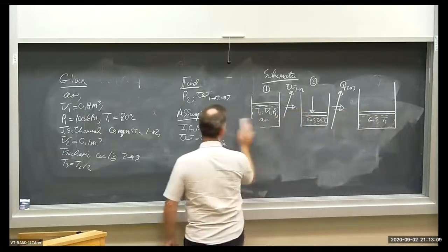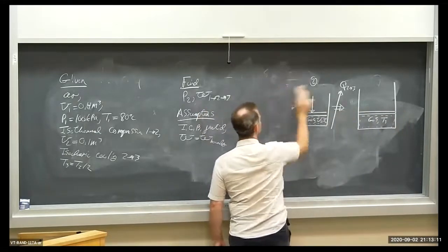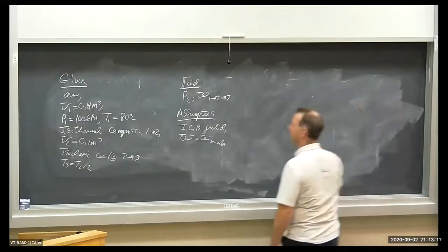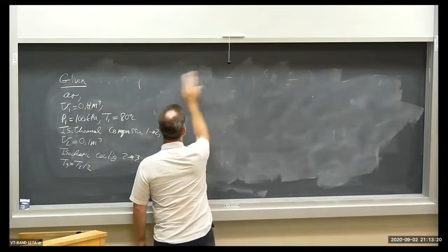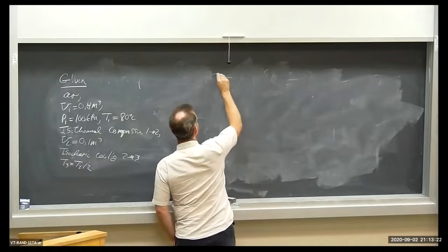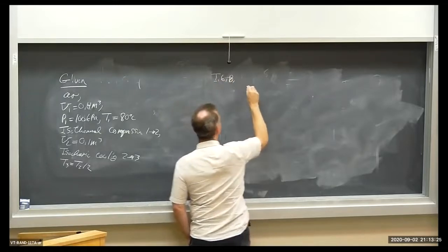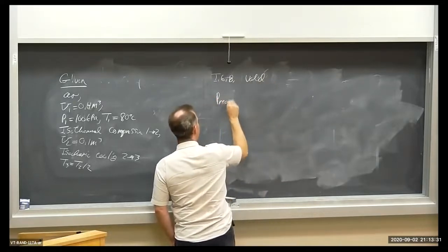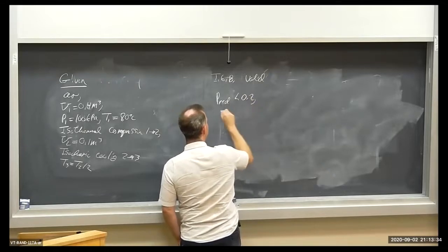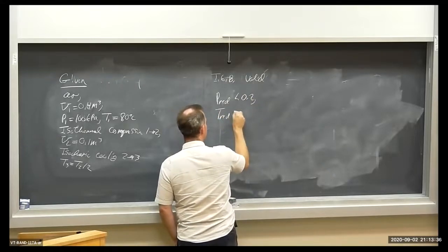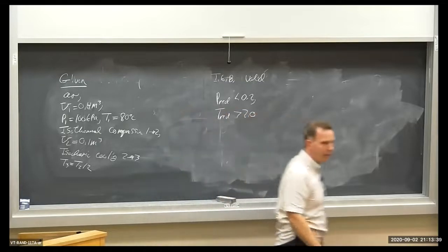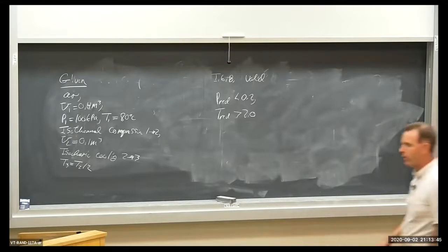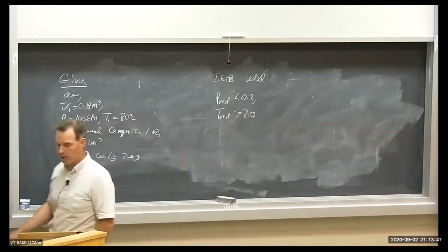First of all, let's check the reduced pressure. Remember, for the ideal gas law to be valid, ideal gas behavior is valid if P reduced is less than 0.2 and T reduced is greater than 2, okay? You're safe. Z is approximately equal to 1, and your answers are going to be good to within 1% or 2% if these are the case.